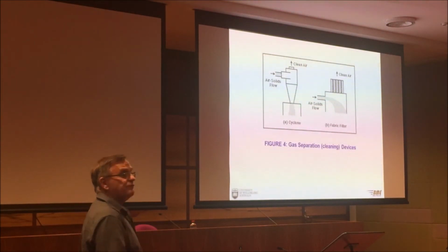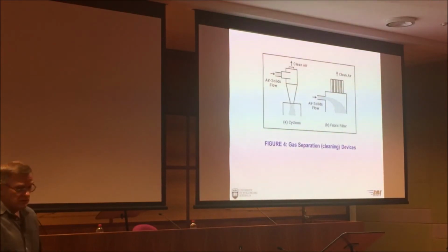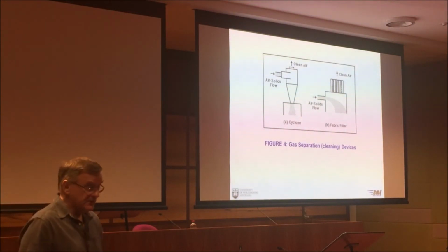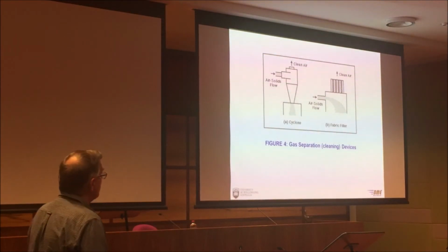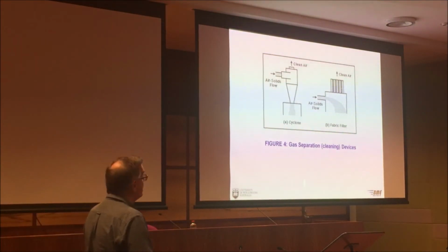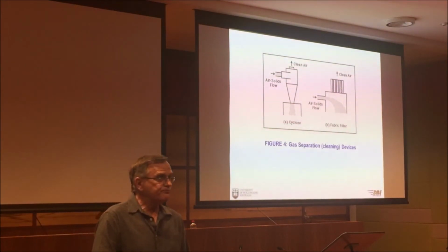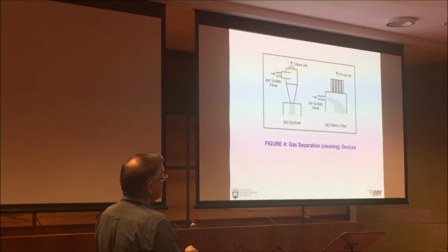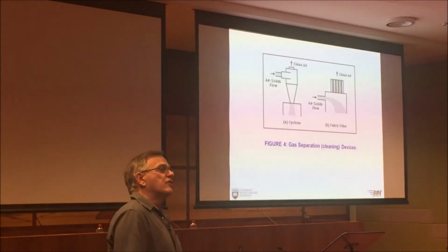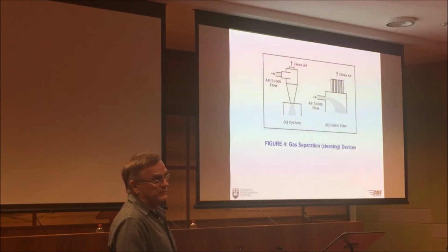So I haven't got time to talk about filtration and how we design these things, select them, but generally with the more stringent emission requirements placed on industry, we require filters everywhere. So you've got to size and select these properly, and particularly if you've got a hot product or hot process, it needs some special attention. And so you've got to work out the maximum airflow through the system, work out your filtration velocity, and then you can size your filter appropriately. And you've got to pick the right filter material for your powder.